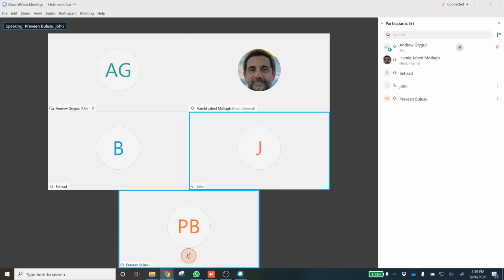Sure. On the other part, you helped regarding the damper housing. As I told you, the parts were completely out of spec because of the inclusions. When the supplier did the CT scan, they found very large inclusions inside that casting, and they determined that was the reason one side was failing and the other side was not. Ah, I see. So it was made in a different die. Yes, because of some minor changes, they have to make the left side part in one die and the right side part in a different die.